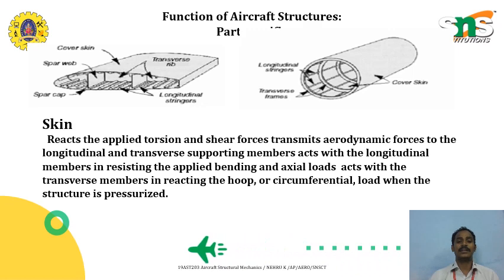Next, the function of aircraft structures. We'll see the different structures. First, we'll go with the skin. It reacts the applied torsion and shear force, transmitting aerodynamic forces to the longitudinal and transverse supporting members. It acts with the longitudinal member in resisting the applied bending and axial loads.